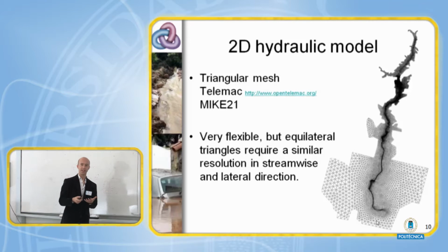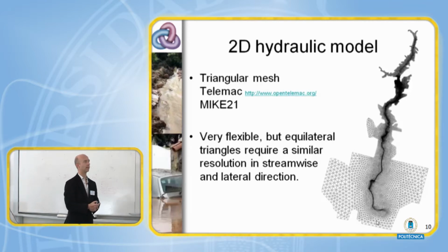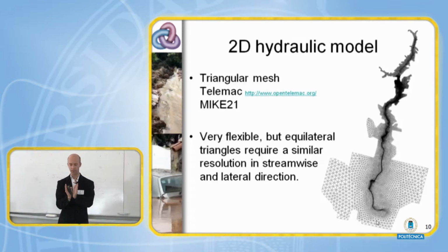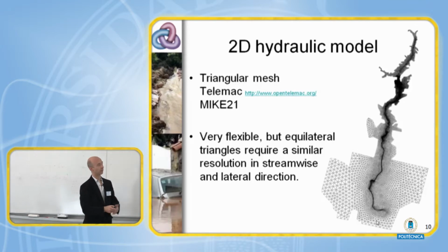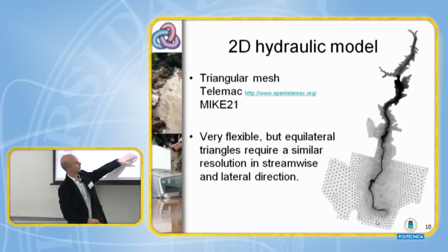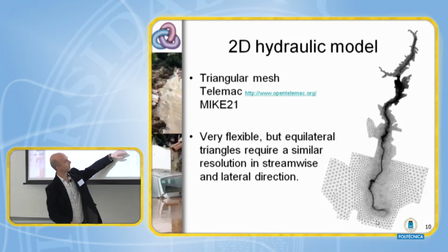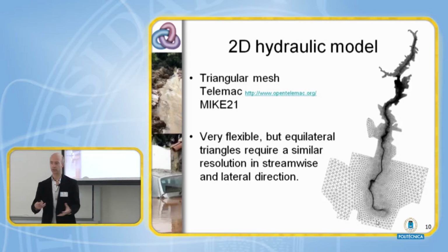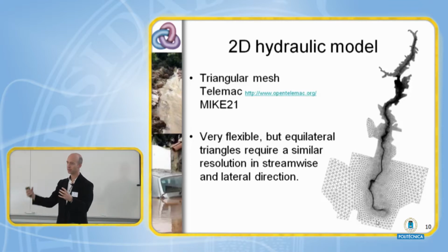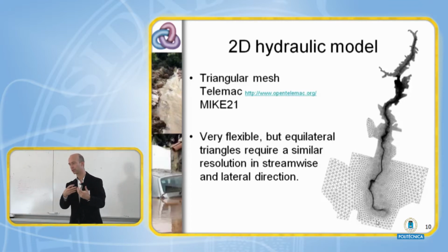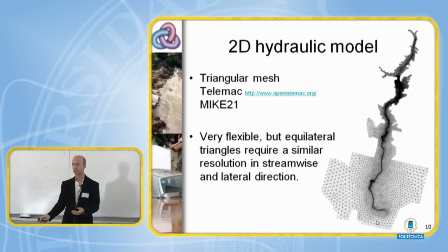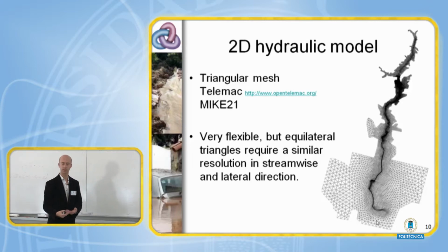So that's limiting the efficiency, and it's also not very nice for your grid interfaces. If you have a predominant flow in this direction, you would have velocity components pointing in all kinds of directions, whereas with a structured grid that follows the channel, you have velocity vectors that align with the grid, and that also gives a better numerical solution.